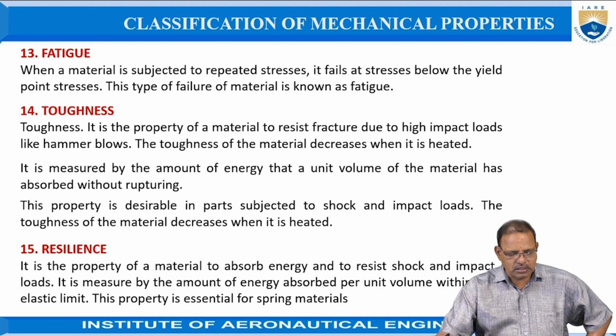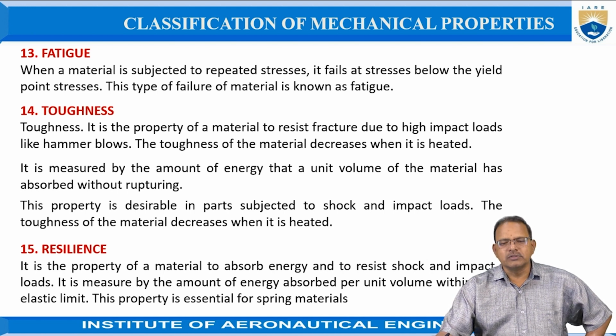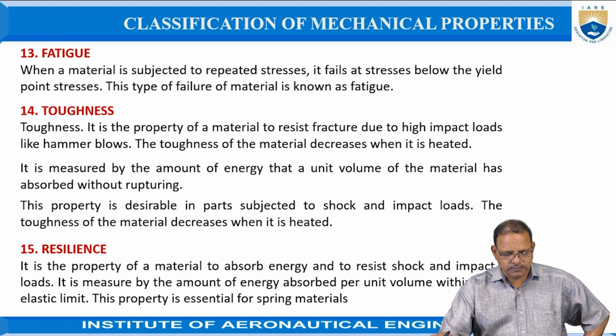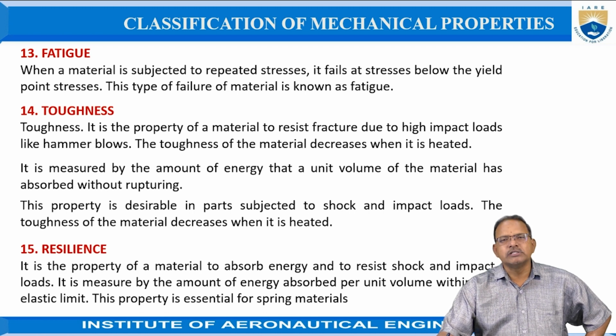Resilience. It is a property of the materials to absorb the energy, to resist the shock and the impact loads, similar to the toughness. It measures the amount of energy absorbed per unit volume within the elastic limit. This property is essential particularly for the designing of springs.